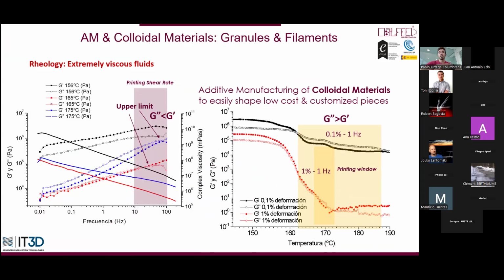And from this, we will be able to establish a printing window where, playing with the optimization of the hopper parameters mainly affected, we will obtain high quality parts without compromising the solid content of the final part. That is quite important for the sintered materials, and without making any bad choice of temperature or printing speed.